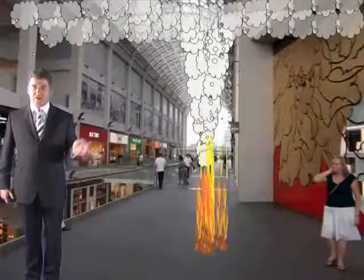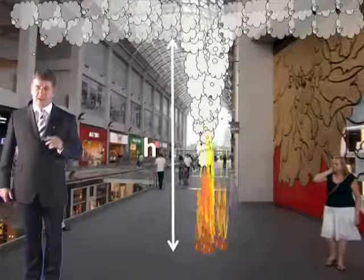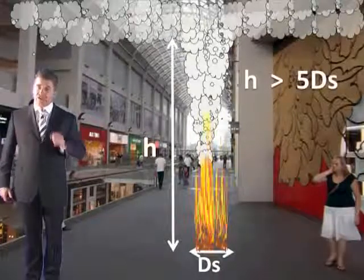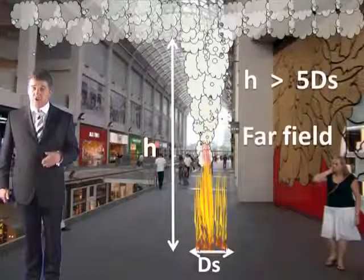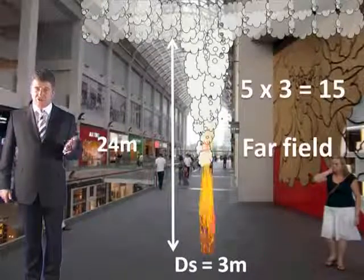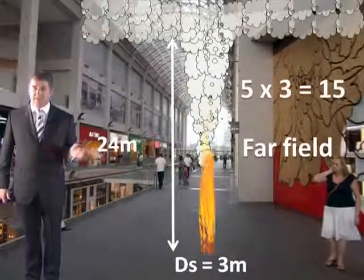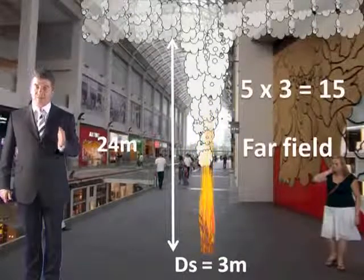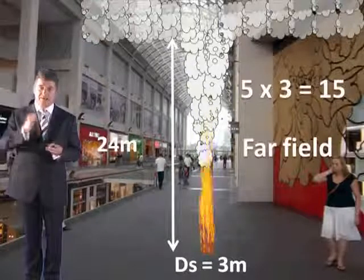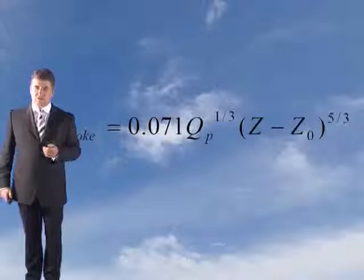Now we need to know whether it's a near field model or a far field model. And don't forget, if the clear layer height is greater than the longest dimension of the source by 5, it's going to be a far field model. If not, it's a near field model. Now in this case, 5 times the longest dimension of the source, which is 3 metres, is 15. And the clear layer height is 24 metres. Well, clearly this is a far field model. So now you've identified not only is it an axisymmetric plume, it's a far field axisymmetric plume. This is the model we've got to apply to work it out.